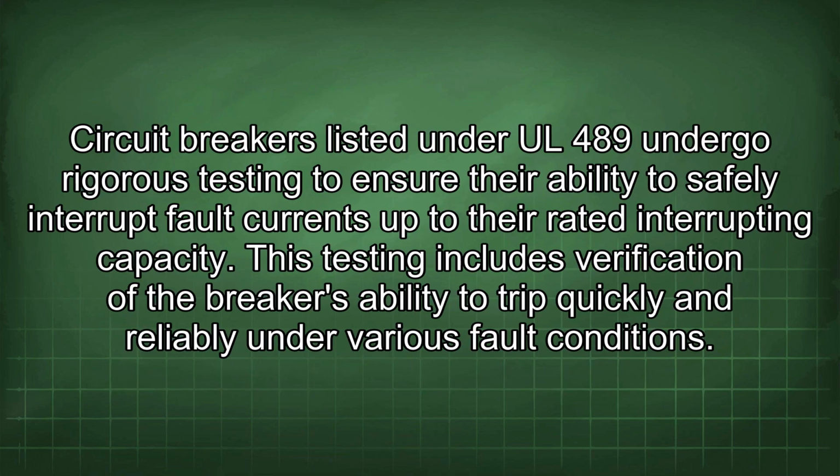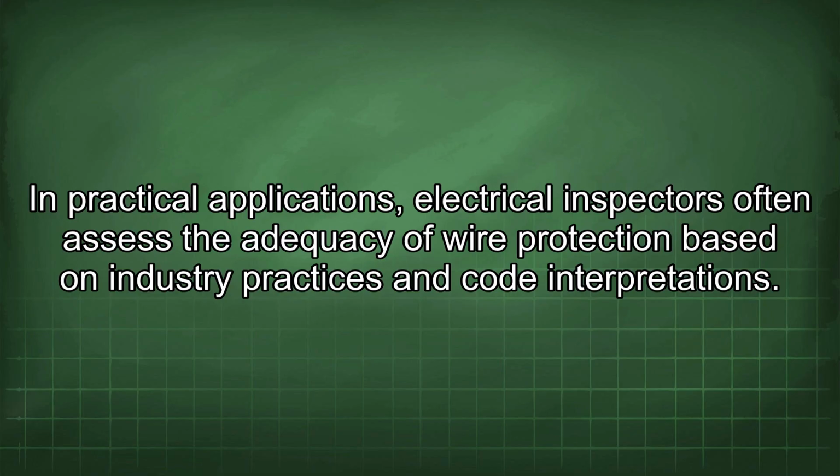Circuit breakers listed under UL 489 undergo rigorous testing to ensure their ability to safely interrupt fault currents up to their rated interrupting capacity. This testing includes verification of the breaker's ability to trip quickly and reliably under various fault conditions. In practical applications, electrical inspectors often assess the adequacy of wire protection based on industry practices and code interpretations.